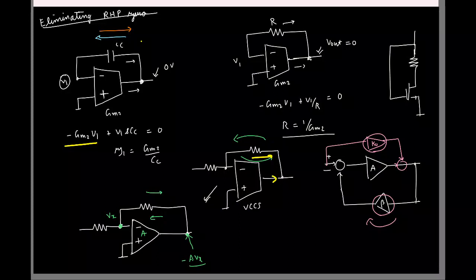If you have a VCVS, the forward transfer due to the elements you put in feedback, that's not a problem at all, because the forward voltage is kind of fixed constant by the voltage control voltage source. Is that point clear? So the bottom line is, if you use a VCVS, it ensures only feedback. And no feed forward.